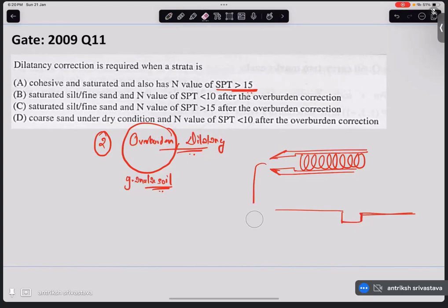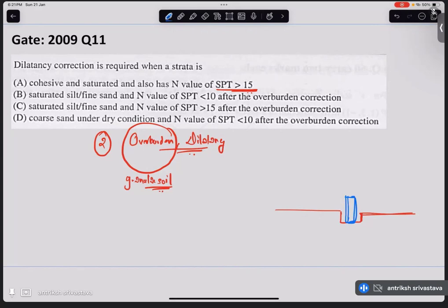Then you can use this sample to do different kinds of tests, such as liquid limit tests and other tests to identify whether the soil is clay, and what its water content is. So we place this sampler on the soil, and we have a shaft on top of it where we drop a hammer. I'm just going in rough terms, and then I'll specify the details of the drop height and all those things.